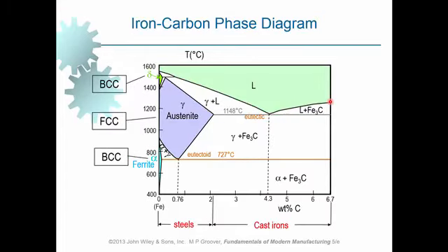Okay. And what is this? Iron-carbon phase diagram. We had this before, right? In Materials Manufacturing 1. Okay. Just helping you to refresh your memory. In this phase diagram, we have the eutectic composition right here. But in this phase diagram, we have another similar point down here. And this is referred to as what? What composition is this? Similar to eutectic, it is the eutectoid composition.